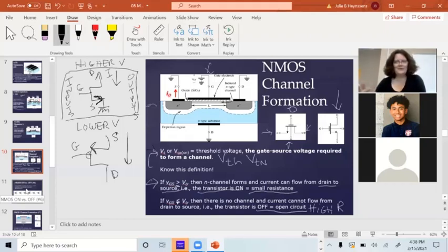Well, at some point you realize PMOS is upside down NMOS. I actually had to build an entire integrated circuit once, entirely using PMOS transistors. They're lower noise, and astronomers really like low noise. But also the logic's inverted. If you've been in my one-time class, you know this: I am a right-thinking, positive logic kind of person. So all of this is negative logic.